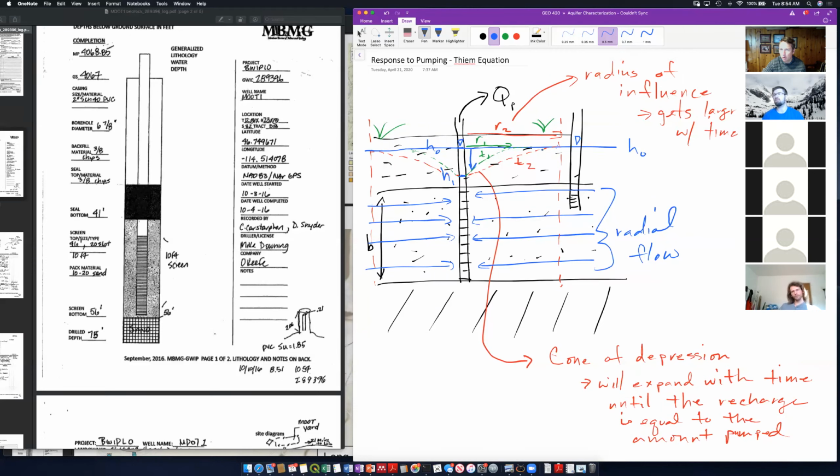So at time 2, you're only pulling water from as far out as my cone of depression reaches. So the water movement's only from this zone in. Out here, it'd still be stagnant because I'm at H naught, all right? So you're only pulling water from where the cone exists. And it comes from the aquifer and into our well.